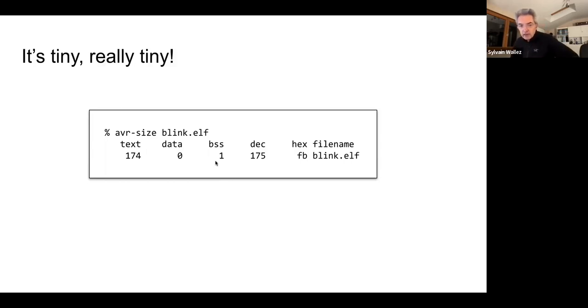And to compare things, I wrote the same thing using Arduino C, and it's 260 bytes big, because the compiler, because of the type system, heavily, and I would say even aggressively inlines everything. And in the end, if you look at the assembly code, we don't even have a function call. It's all inlined, and it's all flipping bits on the registers. Whereas in C, you still have a few layers of function calls that add a bit of overhead. So in that specific case, it's even smaller than C.